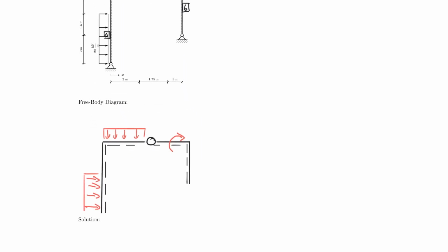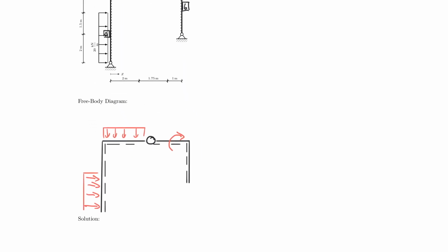And now we can define our support reaction. So I'm going to call this here RAY. I'm going to call this RAX. And it's my convention to always put the forces inside to the frame. And sorry, I confused RAX and RAY here, so let me fix that. Sorry, RBX and RBY. And those are global, right? The X and Y, but we have to deal with the other parts now.